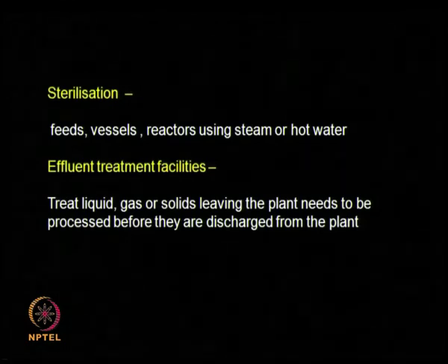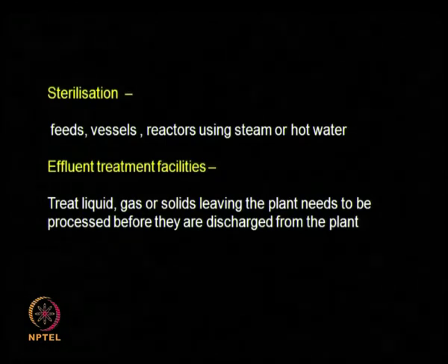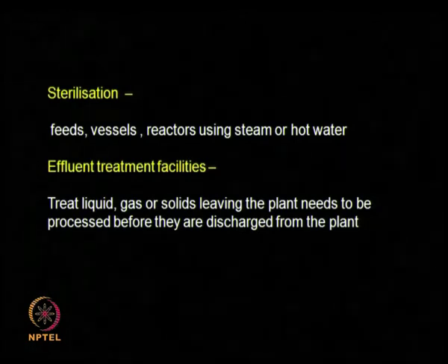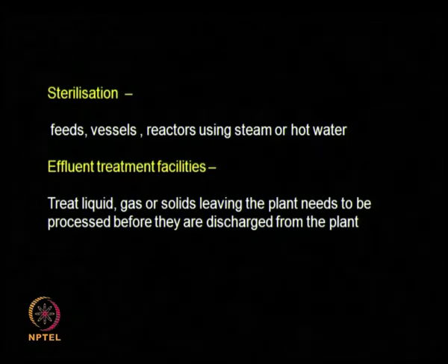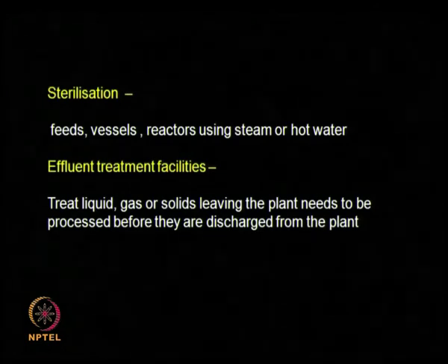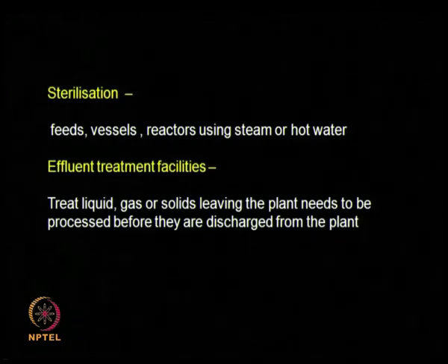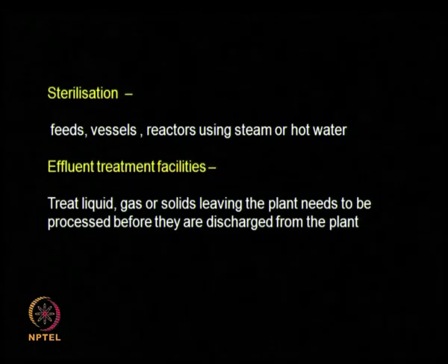Then you will require sterilizing all the liquid feed that is entering the fermenter or bioreactor; it has to be completely sterilized. All your feed vessels have to be sterilized before starting a batch or a campaign. Your reactors have to be sterilized, and all the holding vessels have to be sterilized. So you need sterilization facilities, that means you use hot water or steam to do the job, okay.